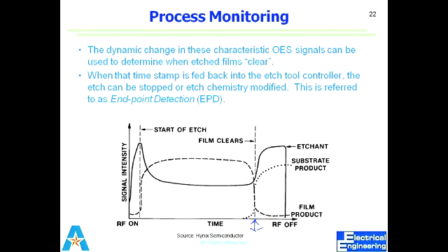By monitoring those specific wavelengths related to certain etchant or certain byproduct, you can monitor in situ what your etched film is at this time, how much is left, or whether the endpoint has been reached or not. You can use either of these two. So it is named optical emission spectroscopy. The name tells that you are monitoring whatever is optically emitted, the emission of certain wavelengths or frequencies, because those are related to certain functional groups coming from the etchant or the byproducts.